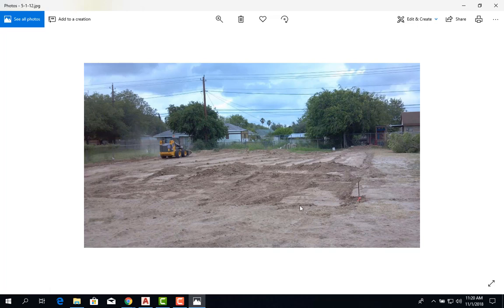You can see it there, and they put the height. And then they go by the plans. The plan says to remove 8 inches or 12 inches, I forgot, or maybe 6. So what they're doing right now is removing all that dirt, getting rid of it. We're going to pull it out, because according to the plans, we needed to bring a different type of soil to provide extra support for our foundation.